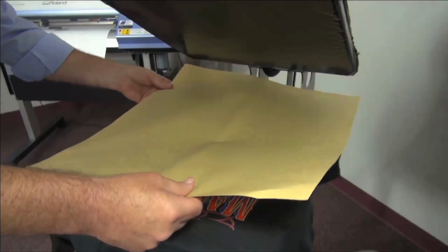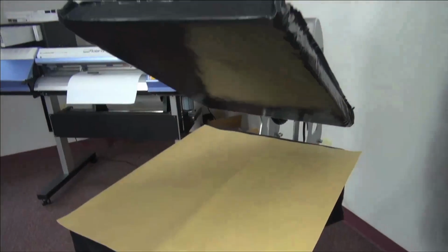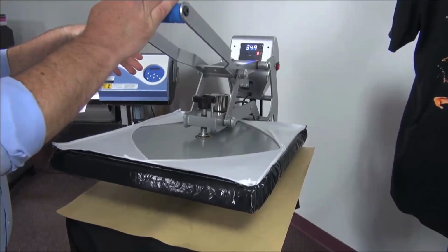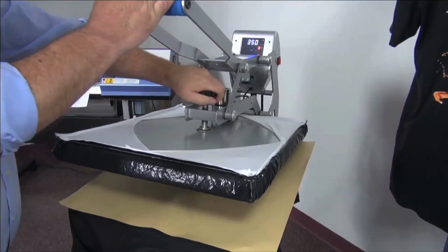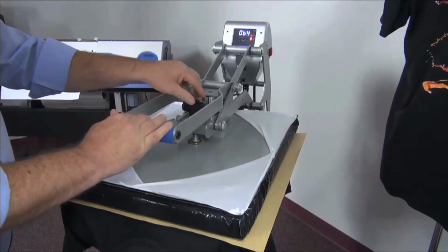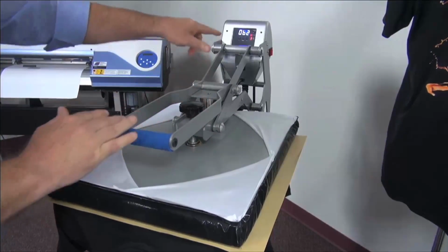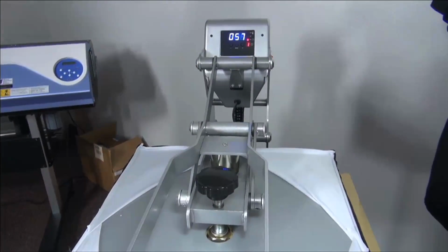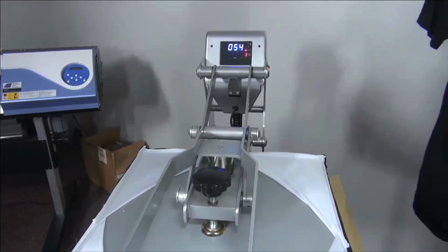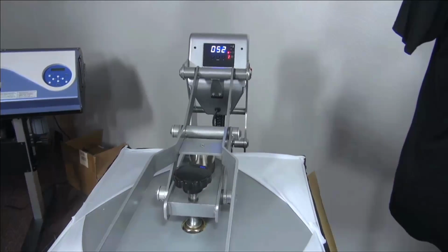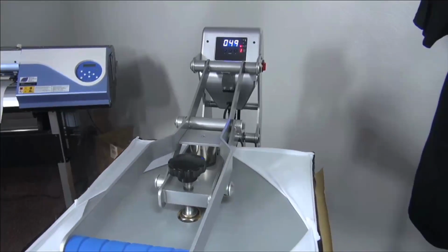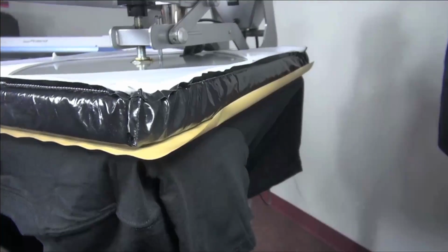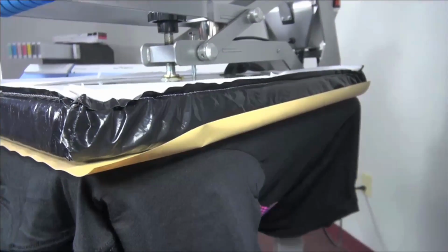We're going to cover it with this siliconized sheet. Now, we're using the same time and temperature that I did to cure the pre-treat, but in this case, instead of the heavy, firm pressure, I'm really just going to kiss this against here and just lock it down just till I register about a 1 or barely a 1 on there. All we're doing is just curing that, drying that ink. Not just drying it, but it has to achieve a certain temperature to permanently cure, so it's very durable. The steam vapors that you see coming out of there are nothing more than just the water coming out of the water-based ink vaporizing so that it's curing as it goes.